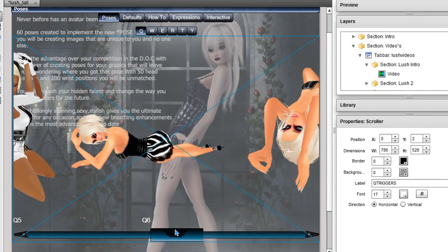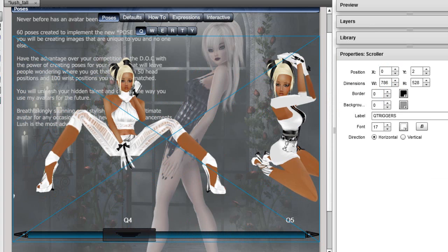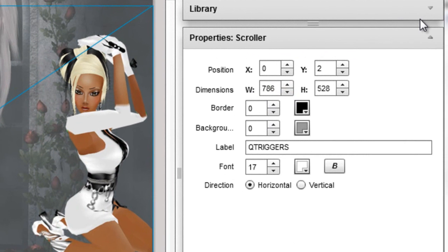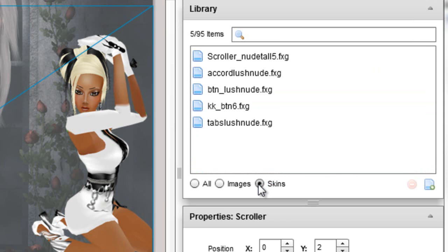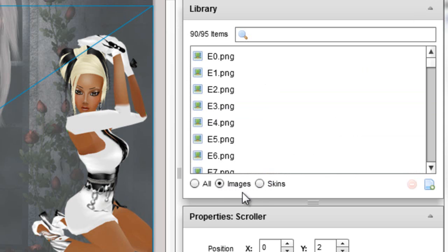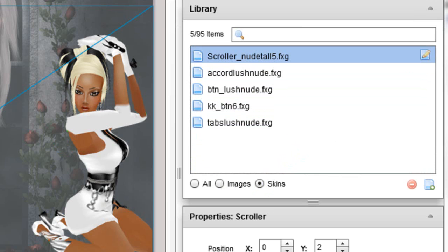This particular skin here on this scroller was custom designed in Adobe Illustrator and imported with the new FXG format that's available for parsing on the Flex 4 SDK. But I had to design my own FXG parsing because that wasn't working properly. So check this out. I'm going to go into skins, and this is my library. I have images and skins contained in here. Skins are FXG files that can be loaded and imported into Illustrator. So this is the scroller skin for this particular scroller.